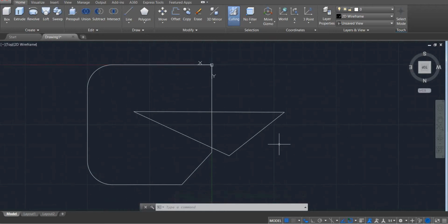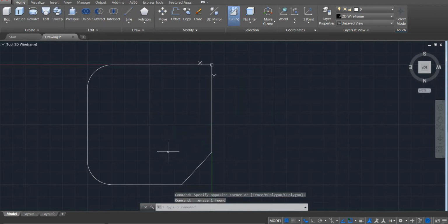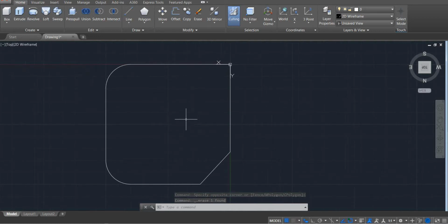So there is a condition here that the thing that should be extruded should be a closed loop. If you decide to extrude something that is an open loop, you will not end up with a solid, and instead you're going to end up with a surface. It's going to be just one surface, but it won't be a solid object. Make sense? This is one thing. So let us work on the first loop first, this one. It is a closed loop, so we can extend it.